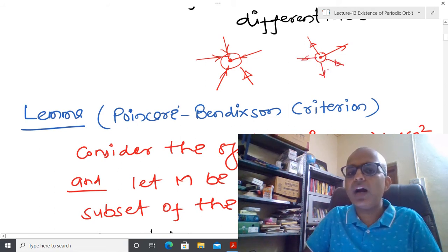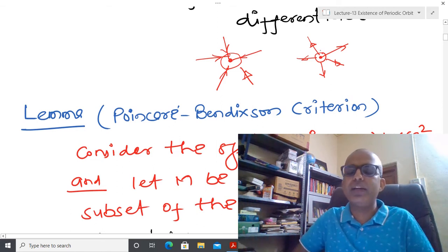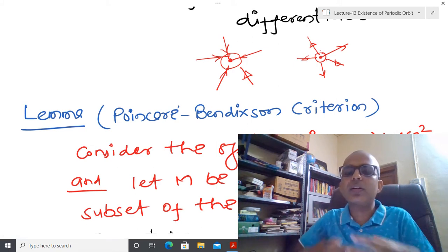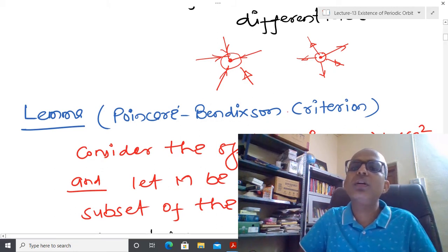Now you can see that in this plane, if something is diverging, it means that locally it becomes unstable. This equilibrium point is locally unstable, we say, because I have already told you that whenever we search the behavior of a nonlinear system, we use the word local only, because I have several isolated equilibrium points in the case of a nonlinear system. So I cannot talk about the stability of the whole system. I am just able to talk about stability of some equilibrium point. So this equilibrium point has some kind of diverging behavior.